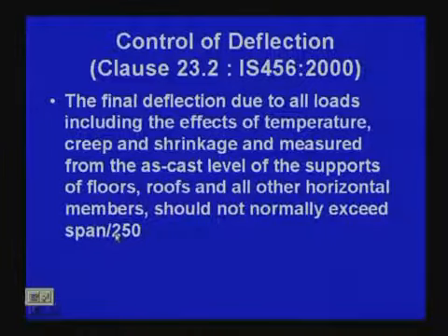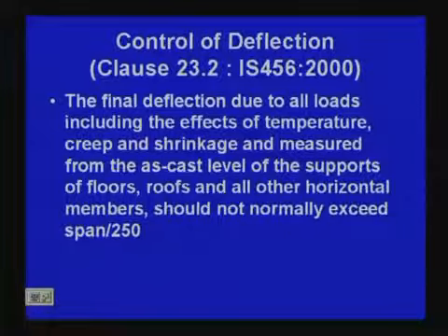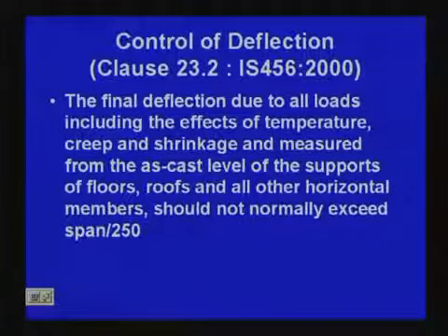That means if we know the span, say the effective span is 3000, you can divide 3000 by 250, and you should take that as the maximum deflection allowed.